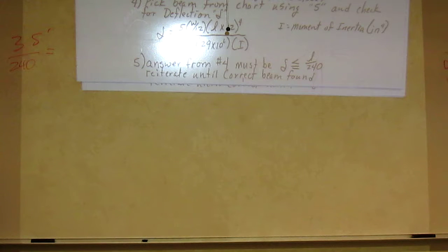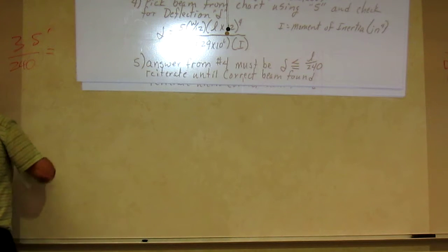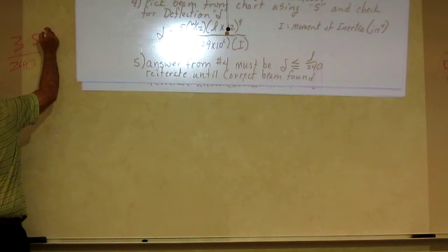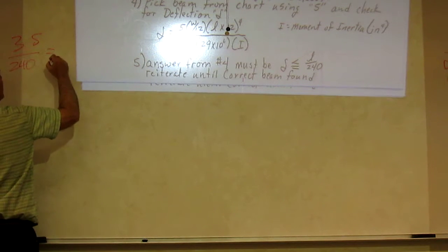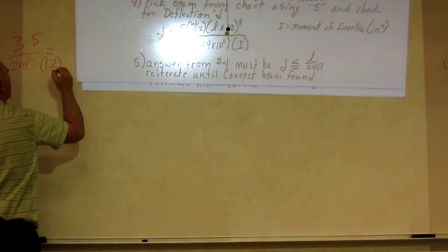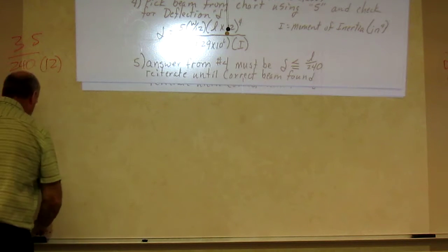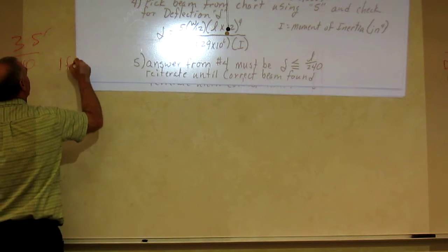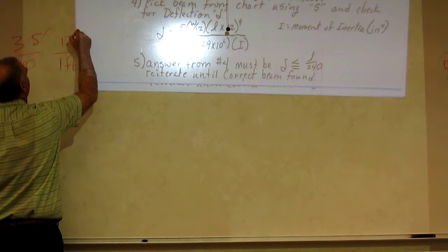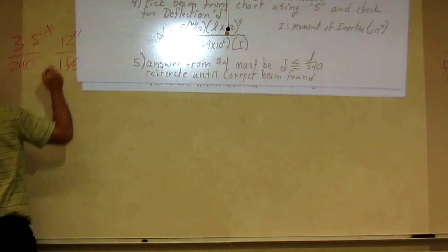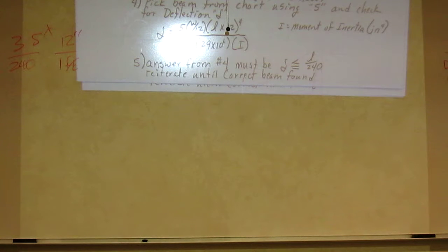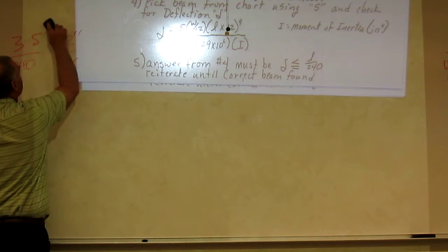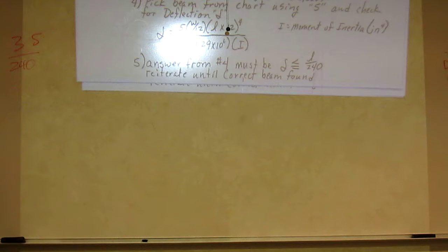1.75, does that sound right? It does. But you forgot something in there on that calculation. This is feet. I know that there is 1 foot in 12 inches. Okay, try that. I did that. I multiplied 35 by 12 and then divided that number by 240. Oh, yeah, that's not the right number. This is in feet. You should be somewhere around 1/4 inch on this.